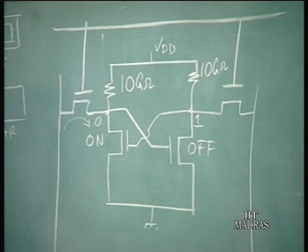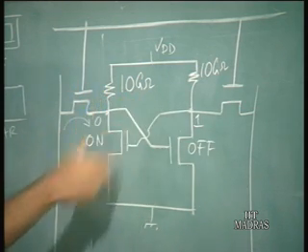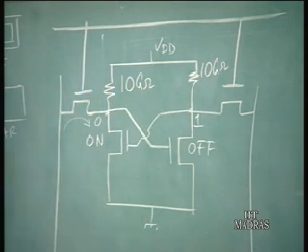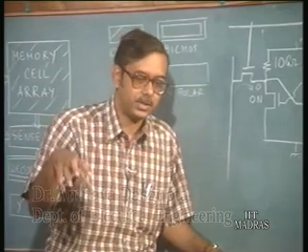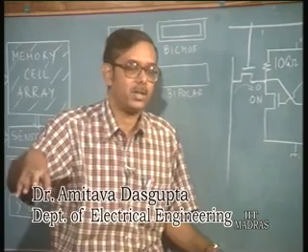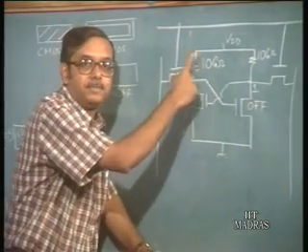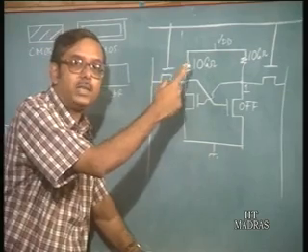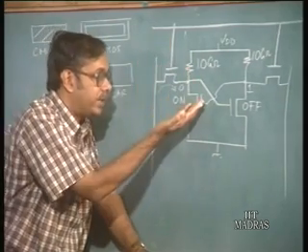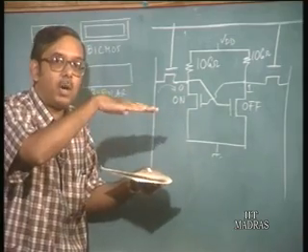Of course, what we do is we avoid the use of PMOS transistors, and you know that in a CMOS, if you have NMOS and PMOS, in order to fabricate them, you have to have 2 tubs, in which in one you fabricate the NMOS and in the other the PMOS. So, that takes up area. In fact, these large resistances are polysilicon resistances, which are fabricated on top of the NMOS transistors.